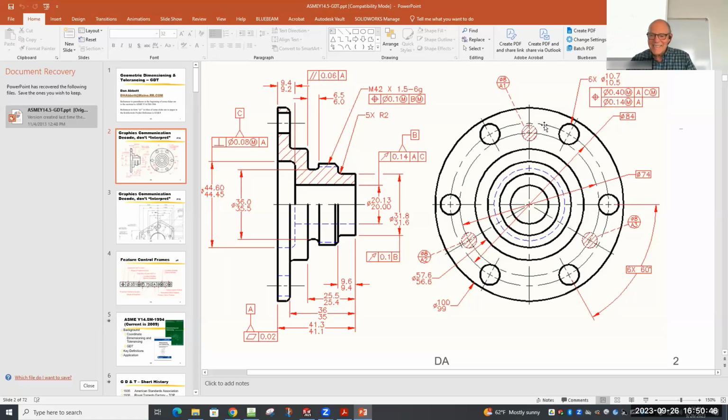One of them controls the entire pattern. And that means if I've got a hole pattern, those six holes there, and I need to bolt that to something, the pattern itself has a location. The entire pattern can move around. If I bolt it to something, it's probably going to have six studs that come out. Those studs can move around as a pattern, and they can move around a fair amount and still work, because as long as all the holes themselves are spaced the same way that the other holes are spaced, everything lines up, even though the part might be moved slightly as a whole part.